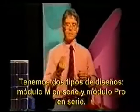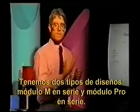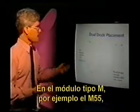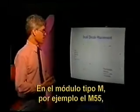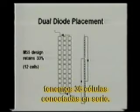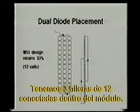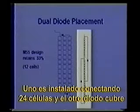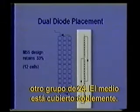We have two types of designs that we offer, an M-series type of module and a Pro-series type of module. In the M type of module, for example the M55 module, we have 36 cells connected in series. We have 3 strings of 12 that are connected within the module itself. There are 2 locations where we can install these bypass diodes. One diode is installed connecting 24 cells. The other diode is installed covering another group of 24. The middle sort of gets covered twice.